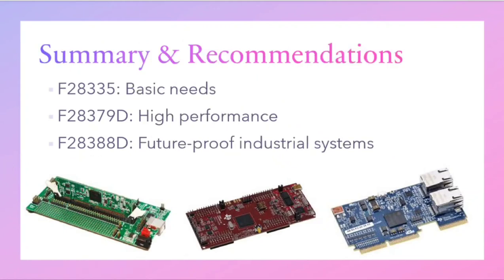So to sum up, if you are just getting started or working on a basic control system, you can go for the F28335 microcontroller. And if you need performance, you can go for the F28379D microcontroller. But if you want performance with future proofing, with communications and real-time control in one chip, you can go for the F28388D microcontroller, and that microcontroller is unbeatable.